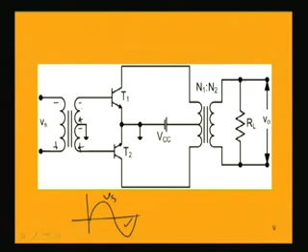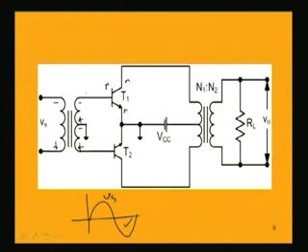That is clear from this polarity of the induced EMF here in the secondary upper part, this P, this NPN transistor, so P is connected to negative, so it will be reverse biased. There is no conduction in the transistor T1, but conduction will take place in the transistor T2, and so we will be having a collector current in the transistor T2 flowing in this direction.